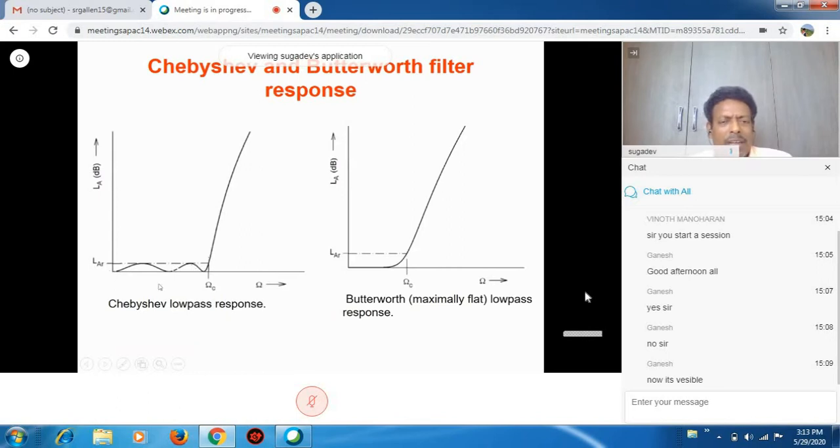And it is obvious from the graph that if you design a Chebyshev low pass filter, you could find some variation in the pass band. Do not get confused with the response here. The response looks like a high pass filter when you look initially, but the y-axis is attenuation and not the gain actually. If the y-axis is gain, then it could be a high pass filter.